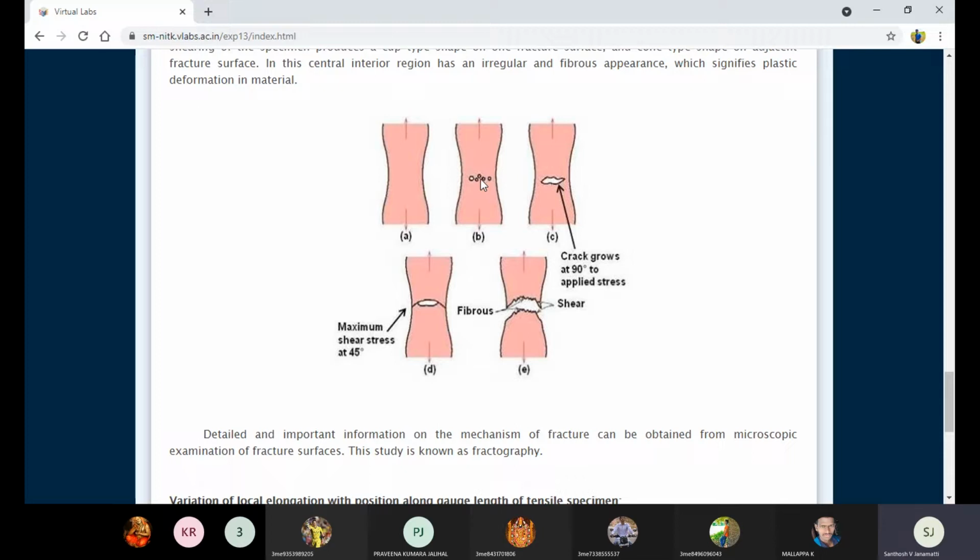So there will be some inclusions or micro cracks. Some holes or micro cracks occur because the cross-section area is reduced, so the percentage of ductility may decrease. As a result, small cracks open at the middle because the cross-section area is less. Hence these micro cracks occur at a certain point of the load.